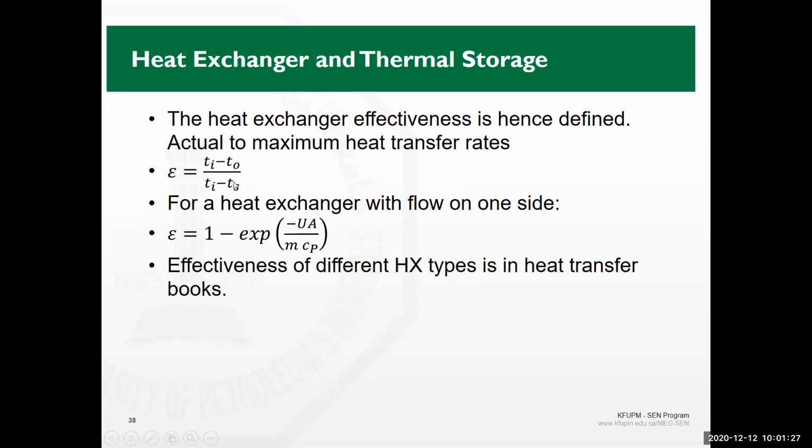If you are able to increase the storage temperature so that it approaches the value of the inlet temperature, then you are approaching 100% effectiveness. Typically speaking, this is not practical, otherwise the storage would have to be very large to increase the temperature to Ts.